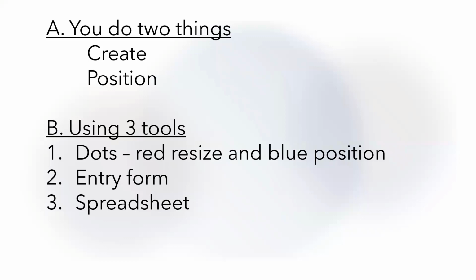And for SketchList, the highest level container is the project. That's whatever you're making, and below that are assemblies. You can think of them as sub projects maybe, but I've come to think of those as organizers. They help me organize my boards and manage my boards. So you create a project, you create an assembly, you may create a door or a drawer, and then you put boards in it. You just put boards in, you cut them to size, and you locate them. So there's really two things: you're inserting and you are locating.